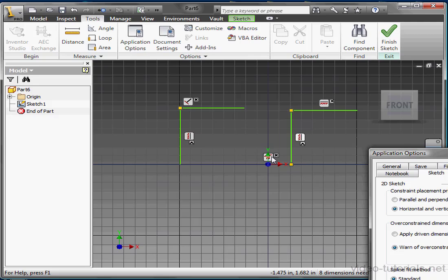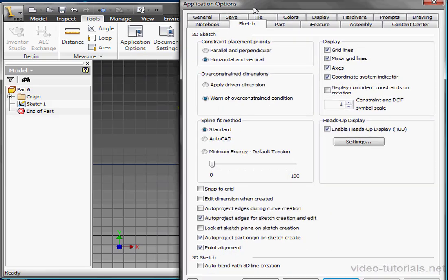You might be wondering where we go to make changes to the sizing of the sketch grid. Here we only hide and show its display. The sketch grid is based upon the units of measurement that you've selected, and that is determined at the file level. We do that in the Document Options window rather than in the Application Options interface.